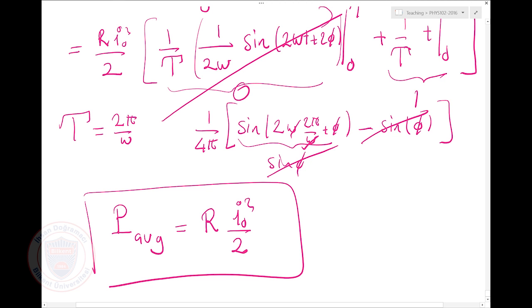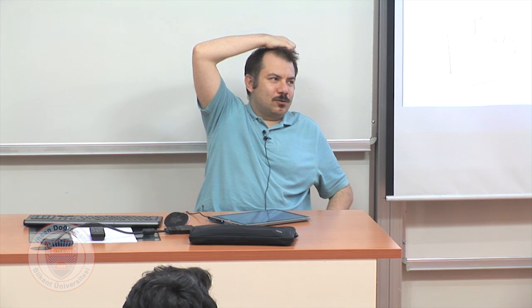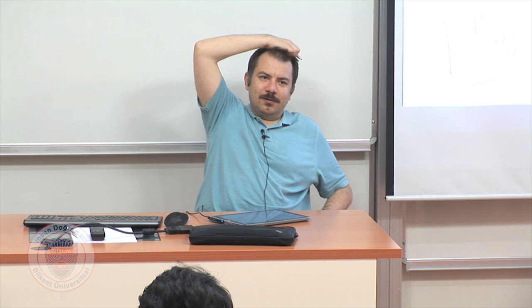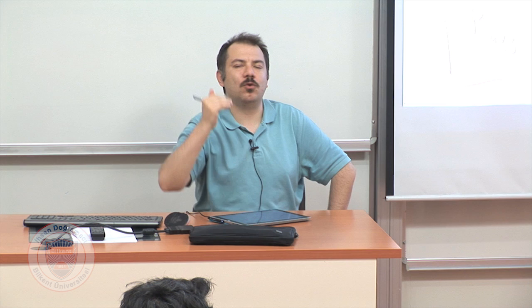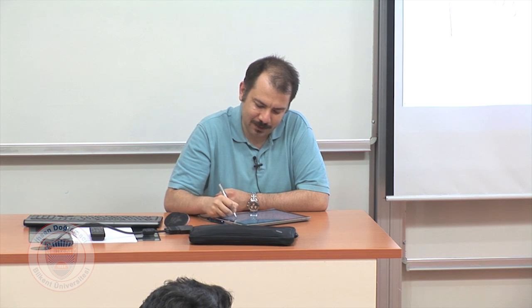Aha. So whenever I have an alternating current, the power is determined not by the peak value of the current, apparently, but by the peak squared over 2. Engineers, for some reason, define something called I RMS, which is I0, the peak, divided by the square root of 2.